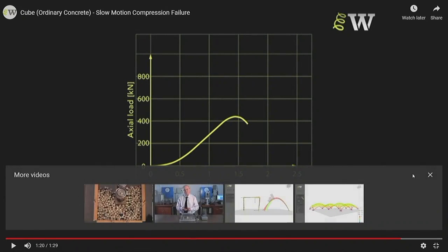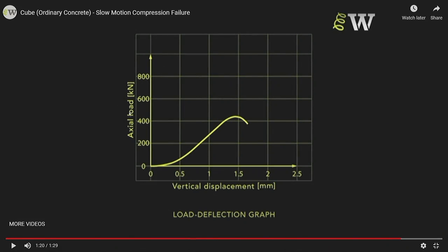So you could see that the load versus displacement behavior in this case is anything but linear to start with. It's very different to the steel, that mild steel one that we've shown. And also, from the peak load, it doesn't stay far. It quickly fails, and the displacement at failure is not much. So this is a typical example of brittle material.